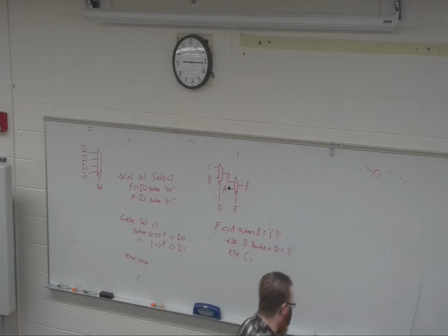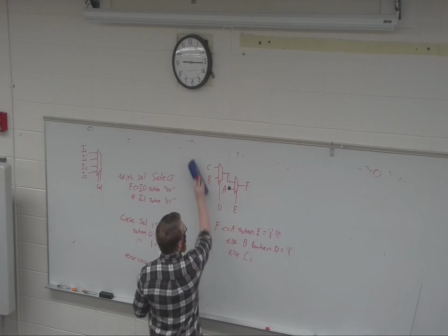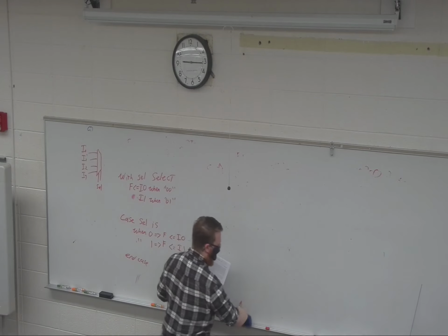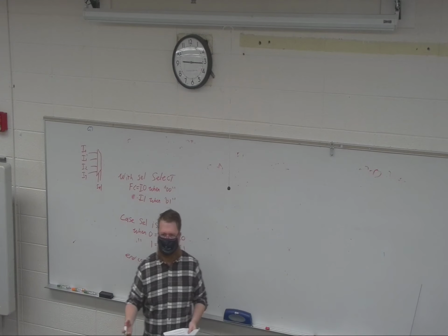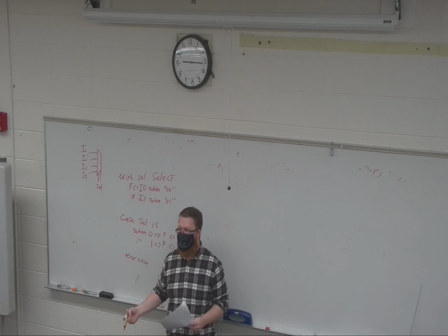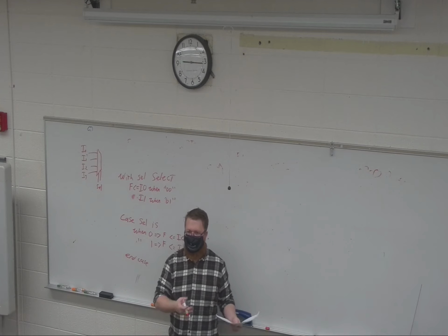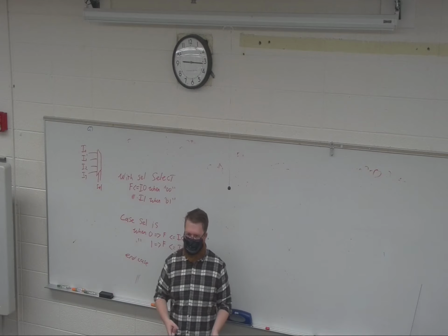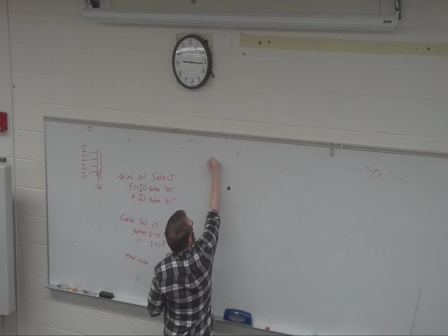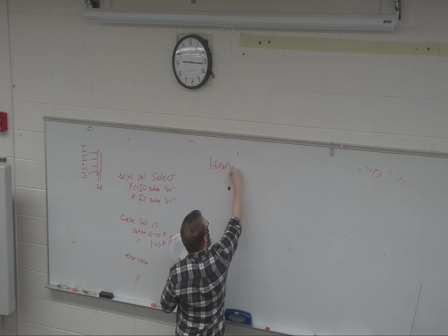Someone asked about this in last class, and I said we would get to it, and here we are. VHDL is weirdly particular when it comes to dealing with types. It is very strongly typed, and it's very picky about what it allows you to do with certain types. It doesn't even let you add bit vectors, which is problematic. So we want to use libraries, which I highly encourage, and this is how.